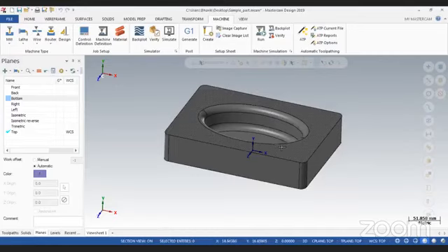So here the workflow is a bit different in case of Mastercam. We need to specify that post processor at an earlier stage, while in other softwares, the workflow is kind of different. In other programming softwares, we can work through this post processing at the end of the program. So Mastercam is working in a different manner. I'm going with some sample details.